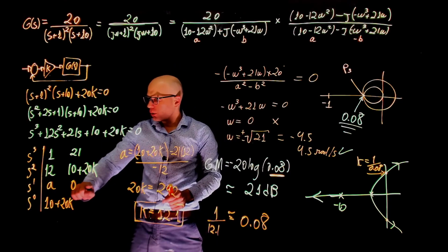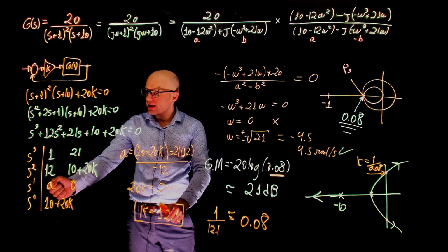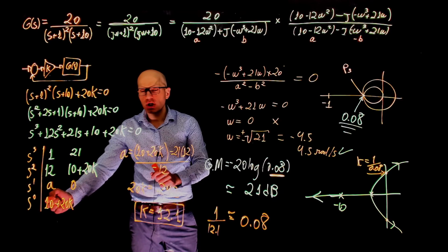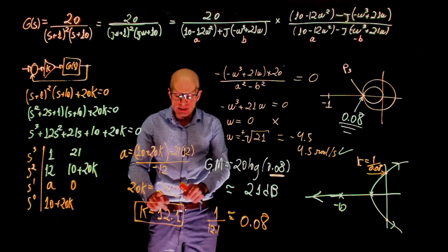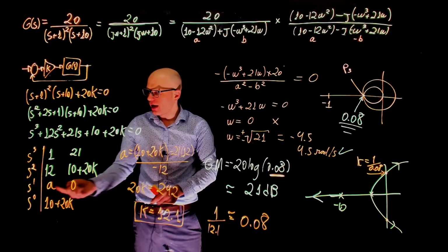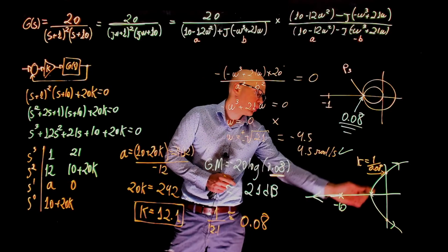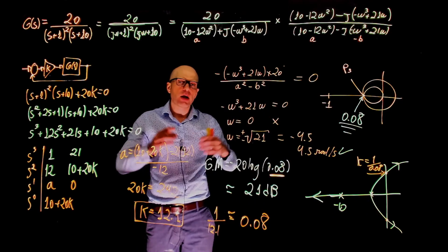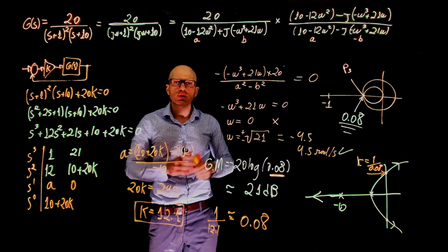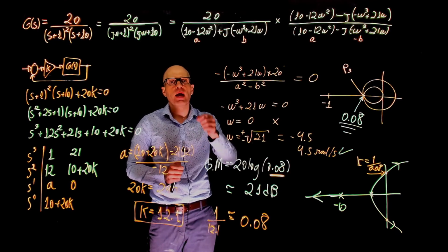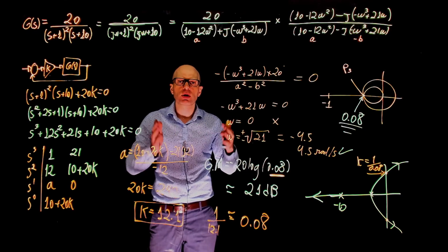We have an entire row of zeros. We have anything greater than 12.1 will make A negative. We have 2 sign changes. The system has 2 unstable poles. When k is exactly this, then we have a row of zeros. We have the Nyquist plot touching -1. We have the root locus touching the imaginary axis. And we have the Bode plot shifting up by 21 decibels and making its crossover frequency exactly happen at -180 degrees. So all these analyses tell the same story.